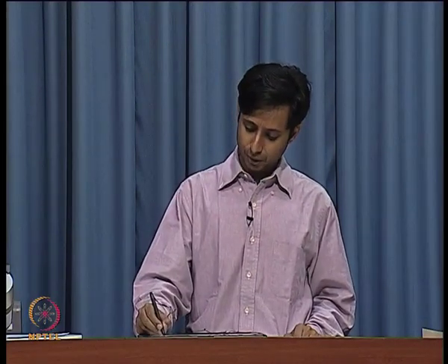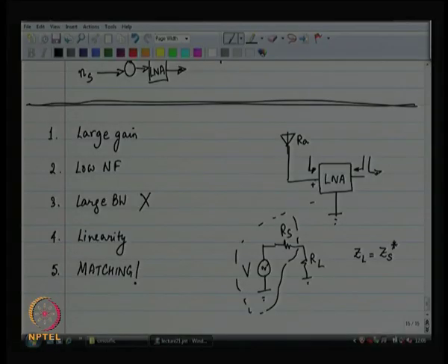Also, the optimum: you can keep decreasing the output impedance of the LNA, and your gain is going to marginally keep increasing, but really, do you want to spend so much in decreasing the output impedance of the LNA to 0? You probably do not want to spend so much. The marginal benefit that you get is probably not worth it. So, in that case the optimum point would be to set the output impedance of the LNA equal to the input impedance of the next stage, or the conjugate of the input impedance of the next stage. So, that is why you want to do output matching.